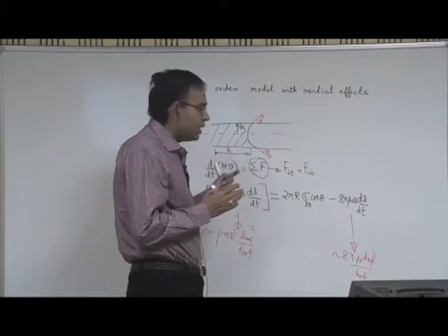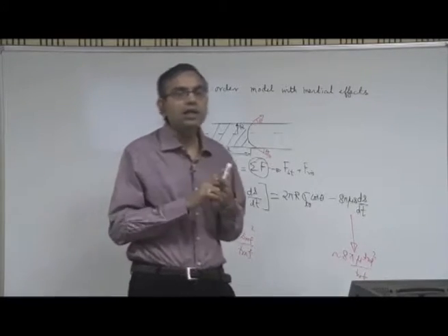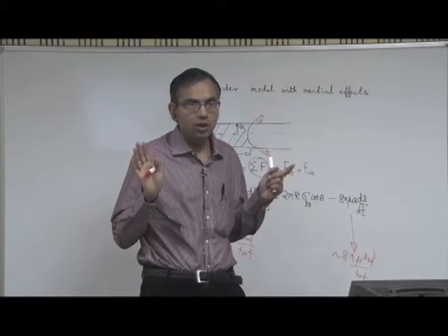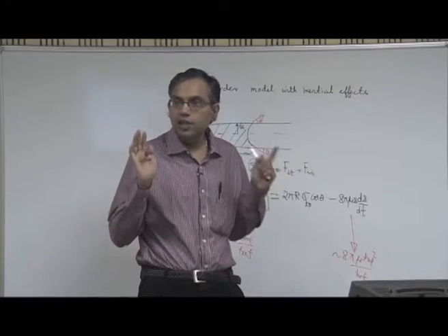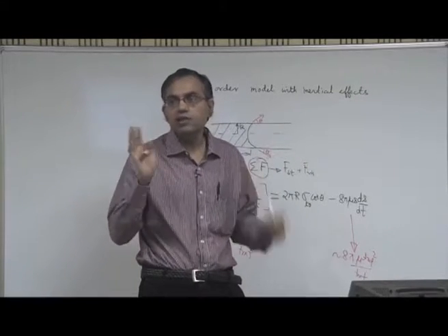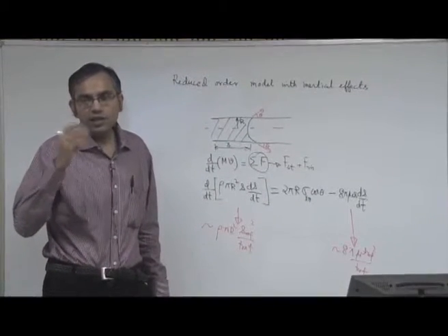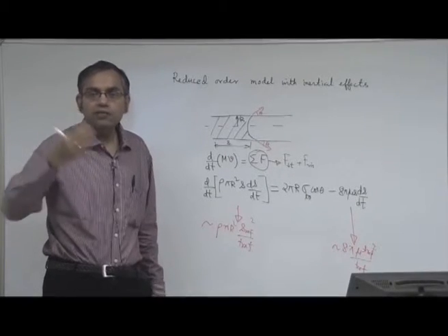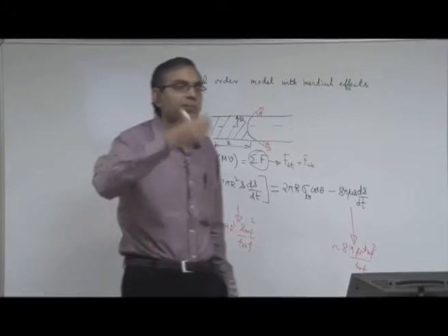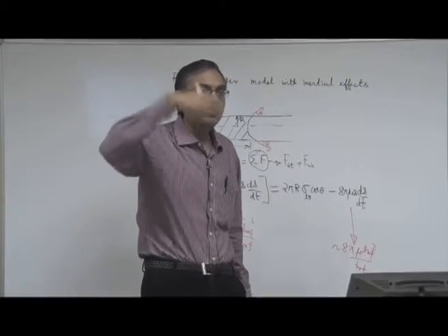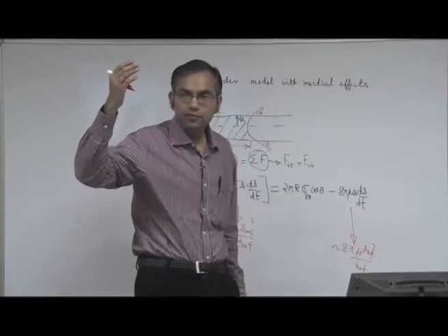See, without the inertial limit, the surface tension force will always be very important. In capillarity, the surface tension force must be important. Whatever is not important is secondary, but whatever is important must be focused. So, surface tension force is always under focus in capillary dynamics. Now, the surface tension force may eternally drive the fluid if it is a driving force, and the fluid will not stop. That would create a sort of perpetual motion, but that will not be possible because the viscous force will come into play as the fluid is moving.